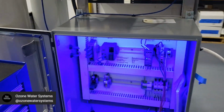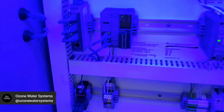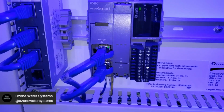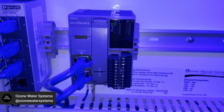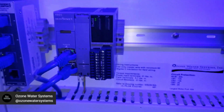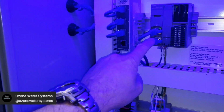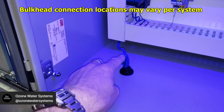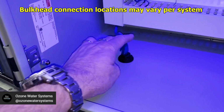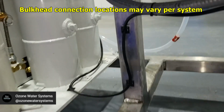This video guide is to show you how to set up the Ethernet IP bridge. It's this IDEC PLC unit, it's an FC6A-D16. It's a PLC, but it's acting as a Modbus to Ethernet IP bridge. Port 2 is dedicated for your customer use, and that port 2 is routed straight down to this bulkhead fitting in the bottom of the cabinet. That's where you'll plug in for your Ethernet IP connection.